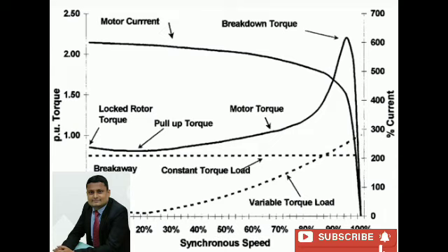Slot pitch at 1/3 height, τs' = πD'/Ss. So tooth width at 1/3 height, that is bt' = τs' − bs. Now area of tooth at 1/3 height, that means width at 1/3 height and iron length.